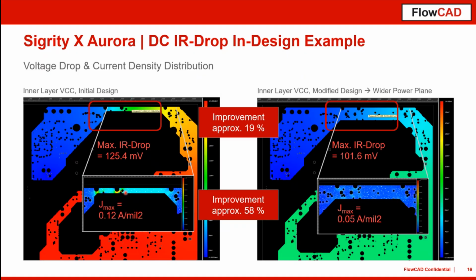But on the other hand, if you can avoid such narrow areas, then you can also avoid such temperature effects, and then you are fine. Such high currents and temperature differences may also cause thermal stress at these areas, and can decrease the reliability of your PCBs.